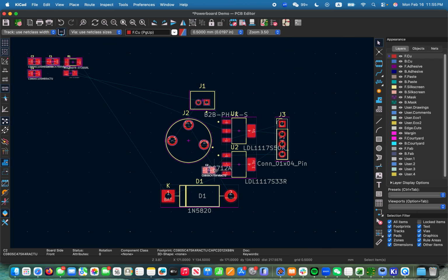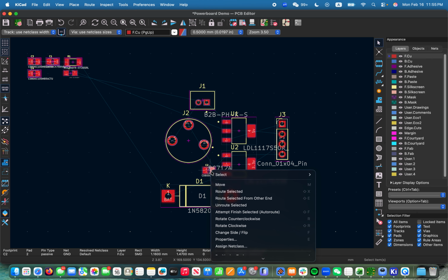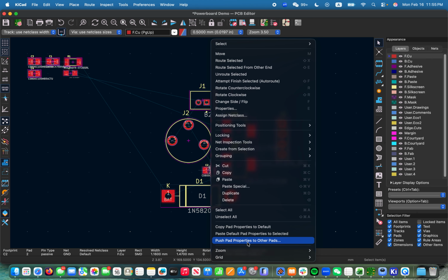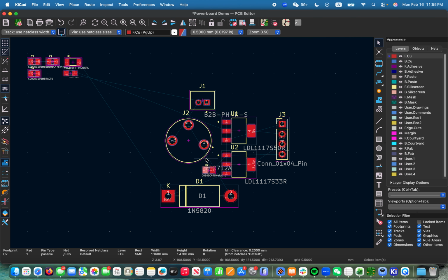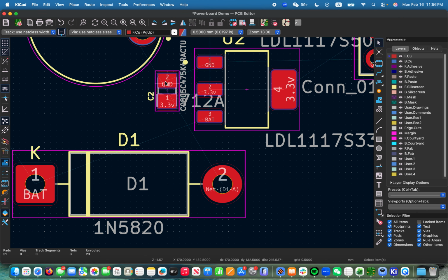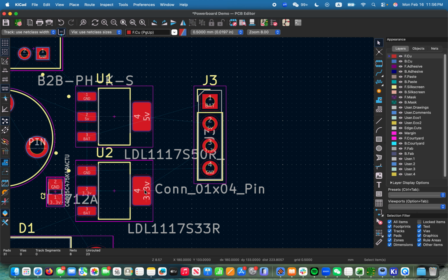So let's press rotate. Oh, how do I rotate this? Oh, there, we can use these keys up here. So Shift plus R. And let's look. Okay, that looks like we're doing a crisscross here. That's not great. So let's do it twice. So now we can see that there is a cyan line going from ground to ground, cyan line going from 3.3 to 3.3 volts. Great.